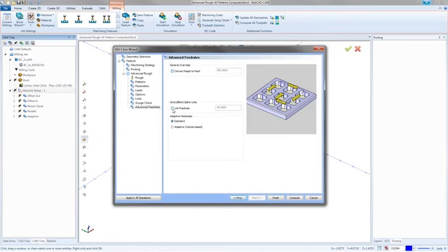Right down here, we have our blend spline links. This is just how we can link our toolpath, our links together, just with a spline to make it a smoother, better transition. And then right down here, our feed rates, we could do standard or we could do volume based. And that's all based on how much engagement that tool actually has. It'll speed up and slow down the tool as it's cutting.